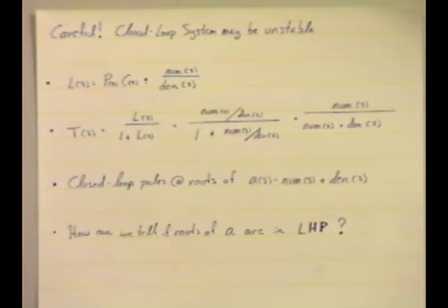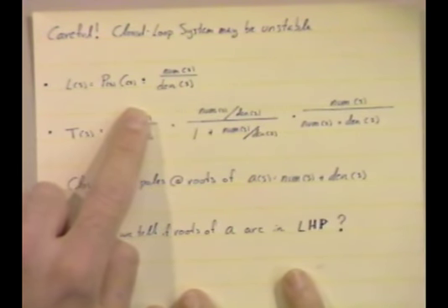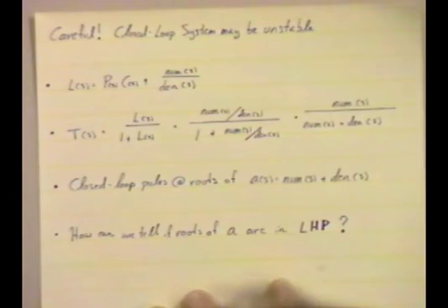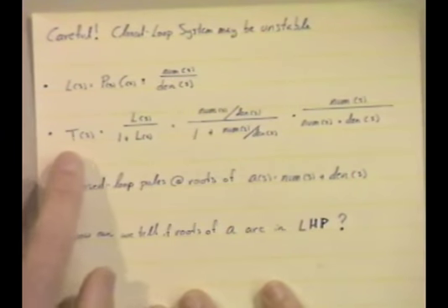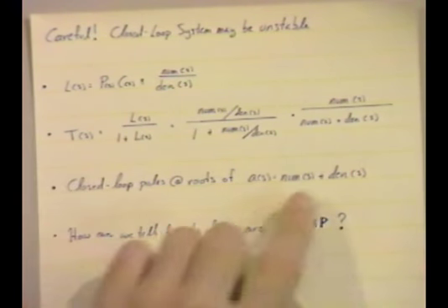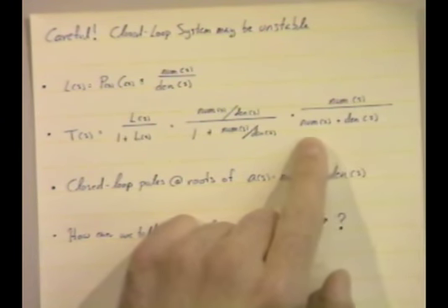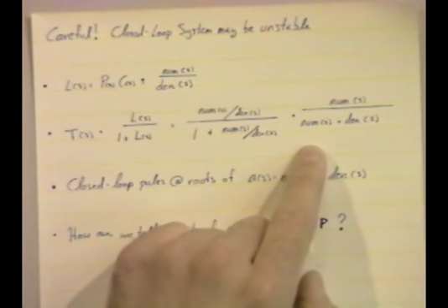Okay, so the idea was that in the closed loop system, you could have unstable poles if you don't design your controller right. And let's see why that happens. So if I look at the loop transfer function, okay, which is the product of the plant and controller transfer functions, and I write it as the ratio of two polynomials that I call num and den, and I plug this expression into the transfer function, I get at the end the following rational function for the closed loop transfer function, where the denominator is given by the sum of the loop transfer function's numerator and denominator, okay?